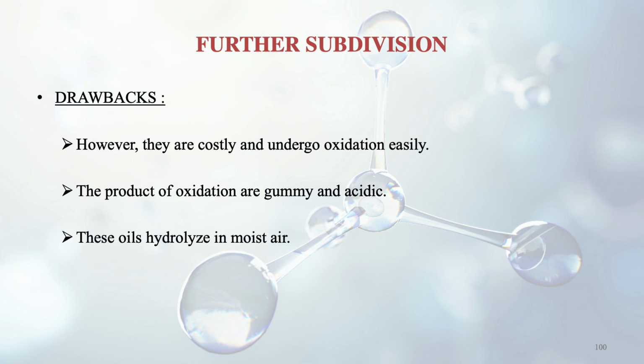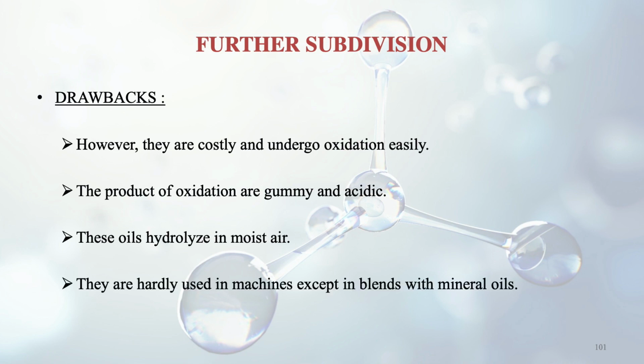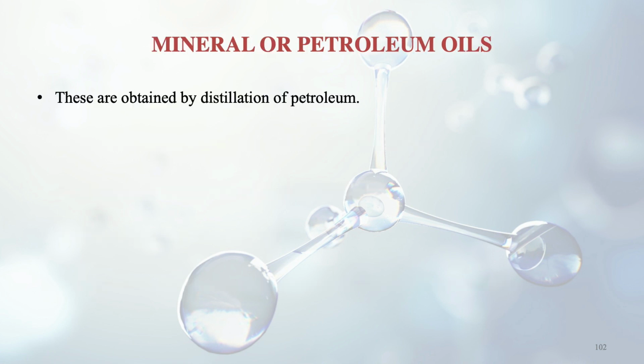And these oils hydrolyze in moist air. So that is a drawback, because then they will have water inside also. And they are hardly used in machines except in blended oils. Then we have the mineral or the petroleum oils. These are obtained by distillation of petroleum.